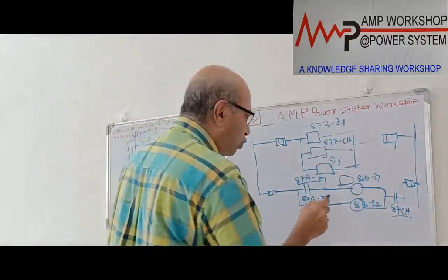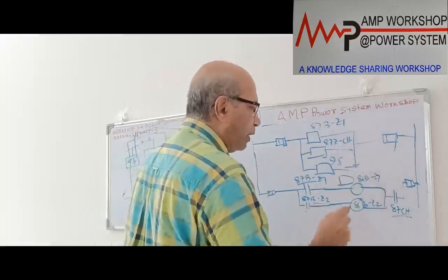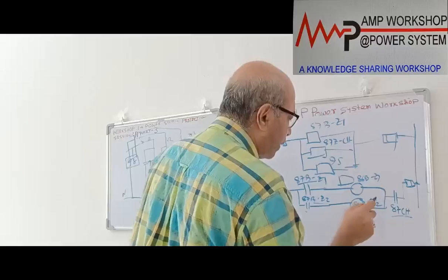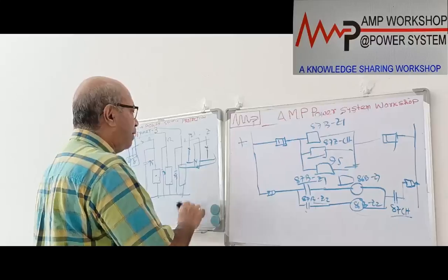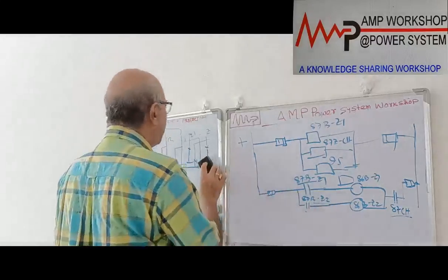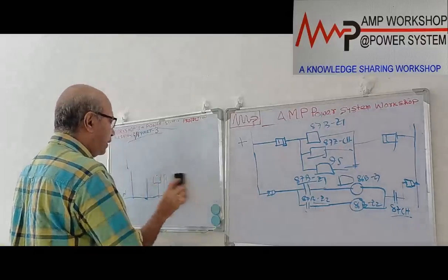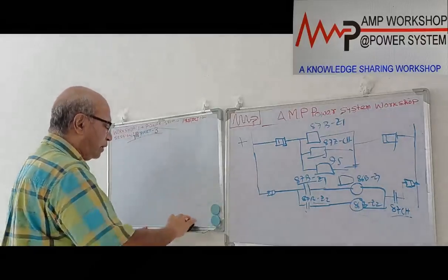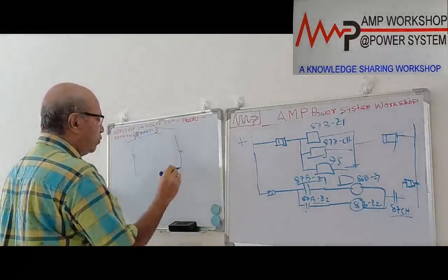And then if zone 2 is operated, this operates the same way. Both operated means both zone 1 and zone 2 lockout relays are operated. When the lockout relay is operated, then what will happen? Immediately this lockout relay will trip all the breakers on that particular bus section, the bus section for which this busbar differential operated. We have already drawn it like this. This is your switchgear.